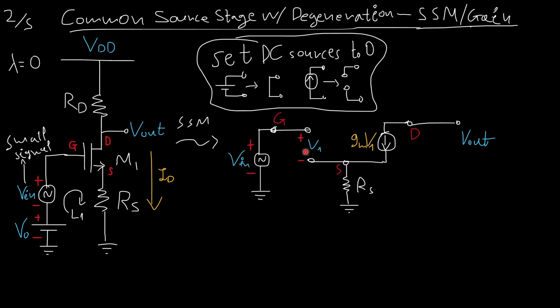I'm going to connect the input signal from here to the gate. This is shorted, all right. This is variable, so it must go into the small signal model. And there is a resistor tied between the drain and the AC ground here. Why? Because VDD must be shorted. I'll write it like this instead.